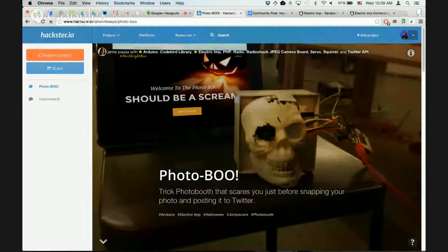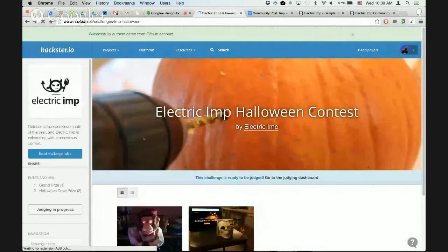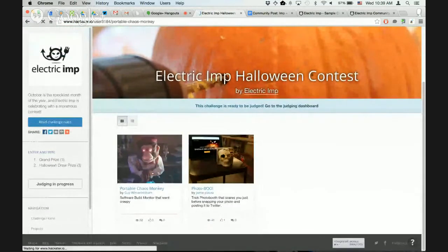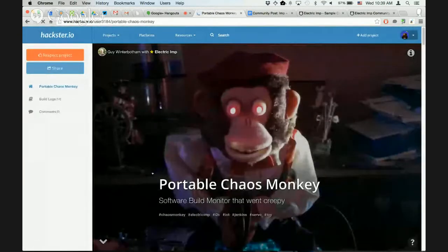And if I remember, there was a bunch of talk on the forum this month about that camera as well, and some of the weird green-purple lines that were showing up. I thought you answered those about getting better quality images out of it. The VC0706 camera continues to perplex people because it's not a super great camera module. There's a number of things about it that are not quite right. A lot of people have picked it up and tried to use it with just the UART, and the code that we've currently published for it is actually pretty old, and it will only work if you hook up the serial peripheral interface to the VC0706.